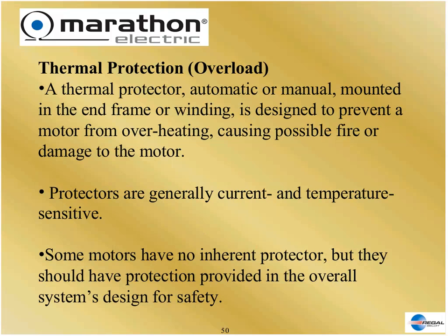Now, let's talk about this part of heat. There are times when the motor is asked to do something that it's incapable of doing. It could be by accident. It could be something has gone wrong in the system. For whatever reason, motors are not very smart, and they are, to a fault, obedient, which means if you ask the motor to do something it can't do, it'll do it anyway, and it will burn up if it's overloaded.